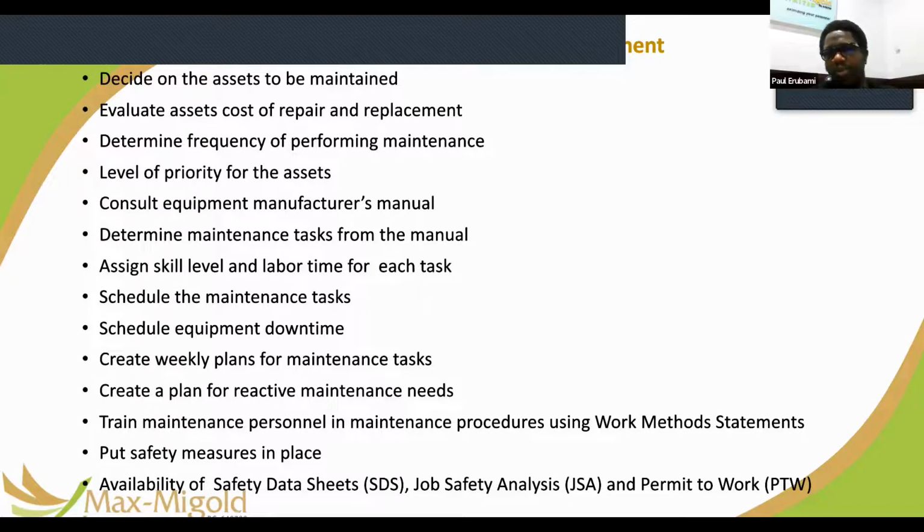Most chemicals are poisonous, and then how to prevent exposure, prevent inhalation, prevent swallowing, prevent contact with skin, and how to mitigate these negative effects if they do occur by accident, right? Those are the kind of things that you see in an SDS. And because you have that and you have trained people on handling those equipment, they will use the proper PPEs and follow the right procedures to work with them.